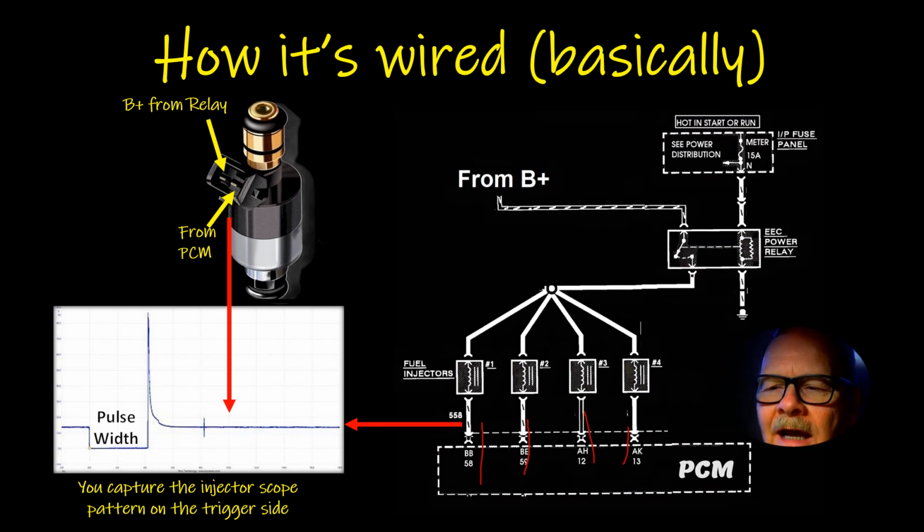But if you tie into that injector right here, you might notice that this area right here is when the injector has not been energized. So you're reading 12 volts right here. Okay, and I can't draw with my mouse worth a toot. I was trying to make a 12 there. But whenever that injector is energized, this is how long it's energized. It pulls it to 0.